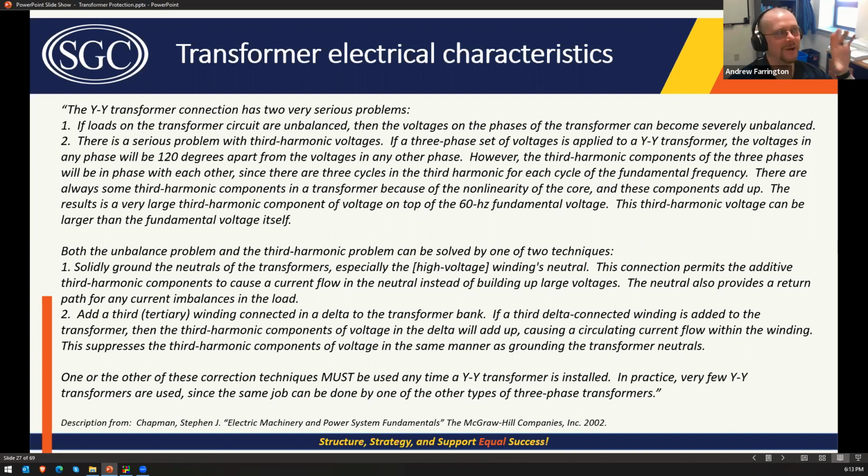You need to know enough to know what you don't know, and to know that you need to go and investigate something, and that you can't just connect a YY transformer in parallel with a delta Y transformer, for example, if that makes sense. Yeah, it takes a while to get to that point to know what you don't know. Sure does.